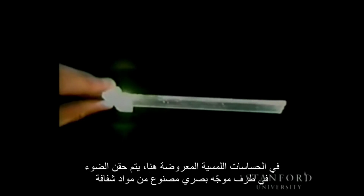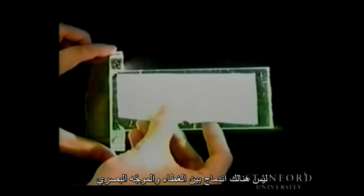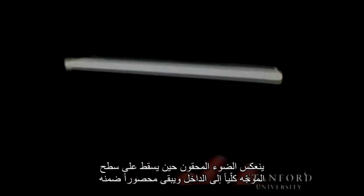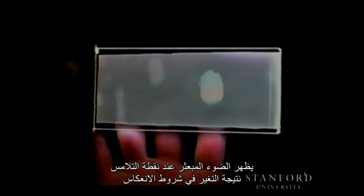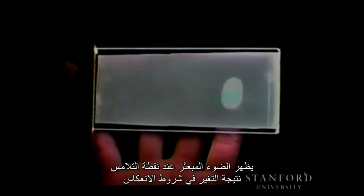A novel tactile sensor using optical phenomenon was developed. In the tactile sensor shown here, light is injected at the edge of an optical waveguide made of transparent material and covered by an elastic rubber cover. There is clearance between the cover and the waveguide. The injected light maintains total internal reflection at the surface of the waveguide and is enclosed within it. When an object makes contact with it, the rubber cover depresses and touches the waveguide. Scattered light arises at the point of contact due to the change of the reflection condition.